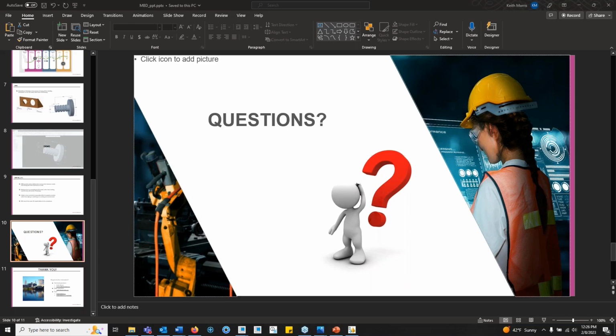Robert Fisher, 3D PDFs: all you would do is go to Save As, and as the type you would change to 3D PDF, and then when you hit OK, there's an option that shows up. You have to select that it exports the annotations with it. I also want to point out you need a full version of Acrobat Reader in order to see the dimensions rotated around with the model. I don't know if a lot of companies have that, some do. So it depends if you have that functionality with Adobe Acrobat.